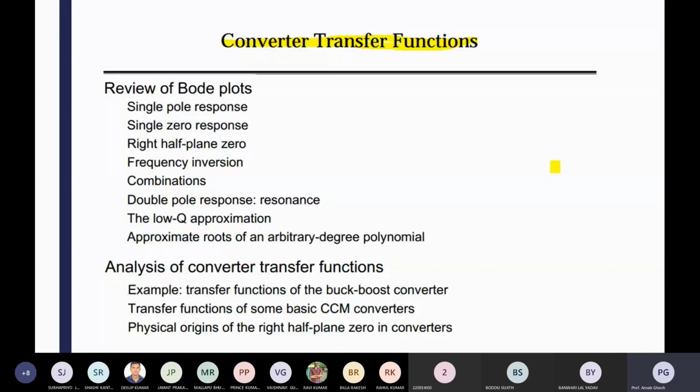So 5 plus 50% of 5 means 2.5, so the input is 7.5. As per your convention, if your converter is robust, your output should be fixed at 12 volts. So we are considering, as the prerequisite, an input of 5 volts to the converter and an output of 12 volts. So how do you make your converter robust?